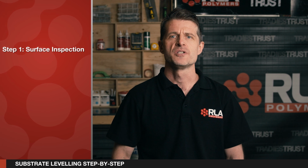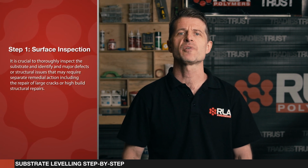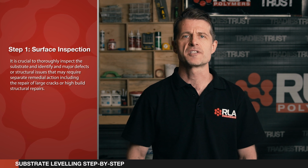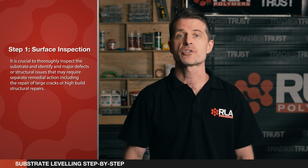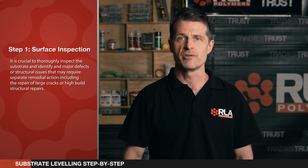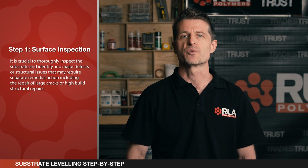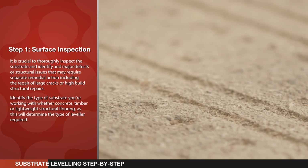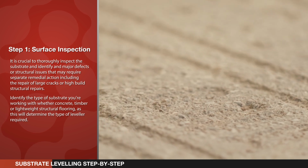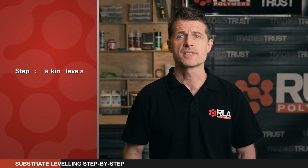Step 1. Surface inspection. As with any application, before starting the leveling process, it's crucial to thoroughly inspect the substrate and identify any major defects or structural issues that may require separate and remedial action. This includes the repair of large cracks or high build structural repairs. Identify the type of substrate you're working with, whether concrete, timber, or lightweight structural flooring, as this will determine the type of leveler required.